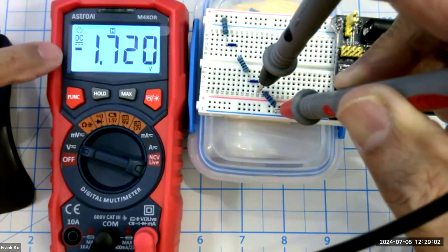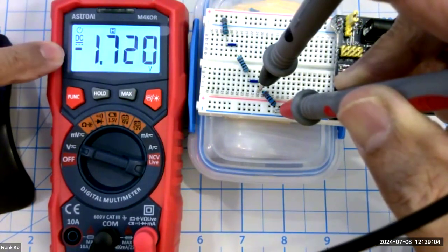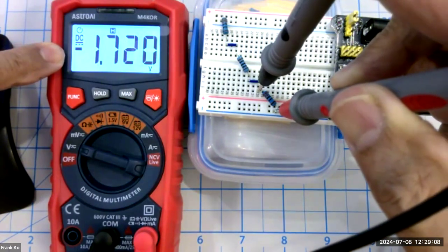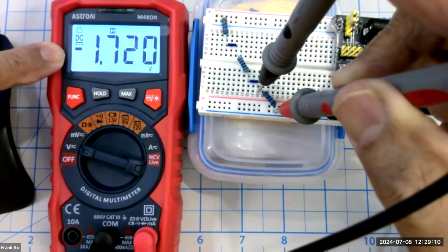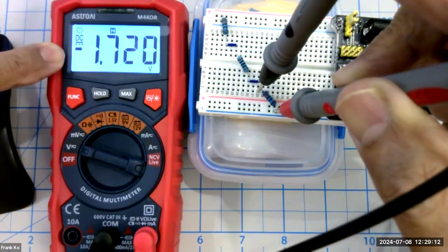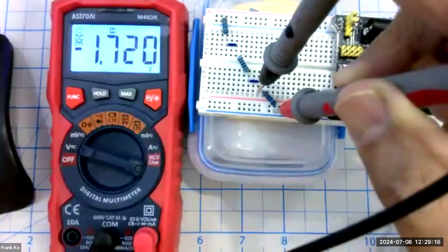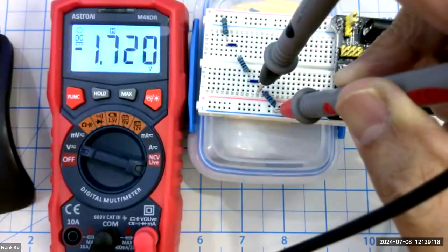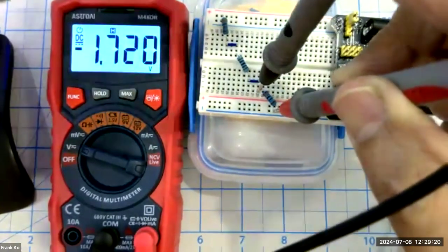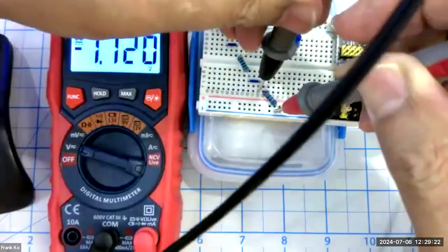Well, I explained before, and if this happens to you, don't freak out. It's not a mistake. All that has happened is your probes are not on the correct polarity for measuring voltage. We said that the polarities don't make any difference for measuring resistance, but for measuring voltage, the polarities of the probes are very important.